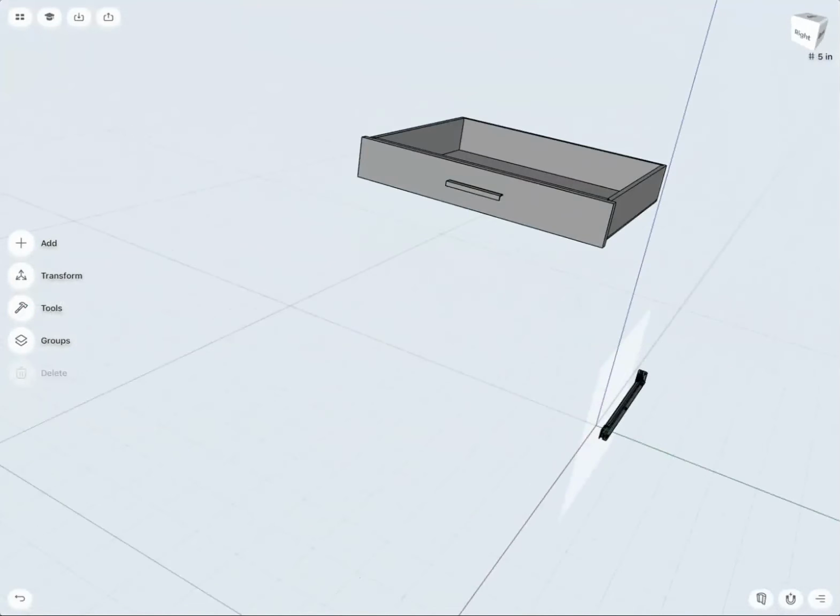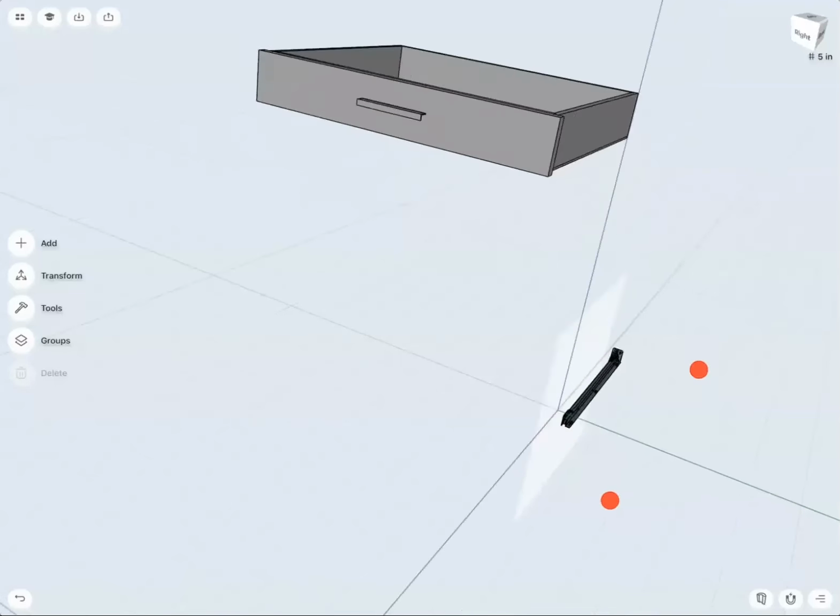So how do I get this one now perfectly snug onto the drawer? Obviously, in this case for furniture design, nothing is really precise to a fraction of a millimeter, because let's say wood, based on the climate, moisture, dry air, will work and expand. So we need to have a little bit of wiggle room, but particularly we want to still work precisely when we need to do positioning of elements when we have to drill holes.